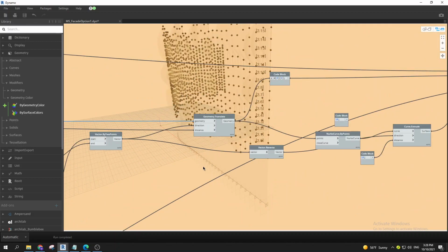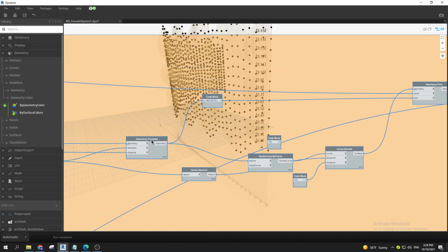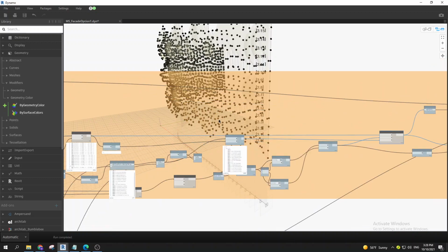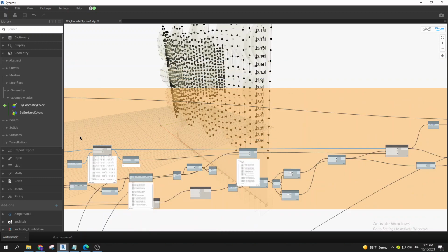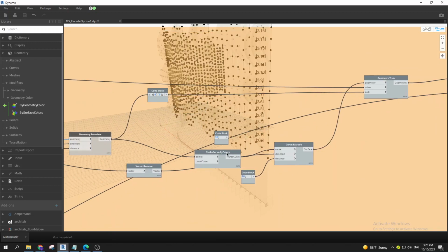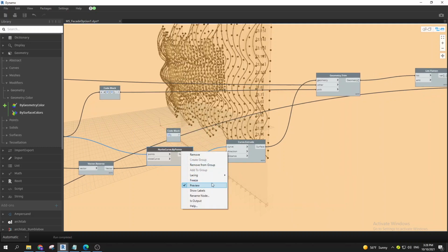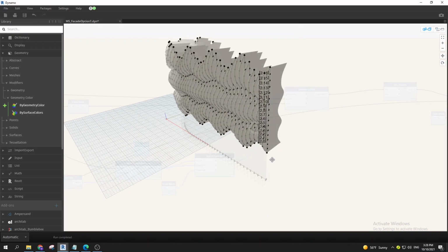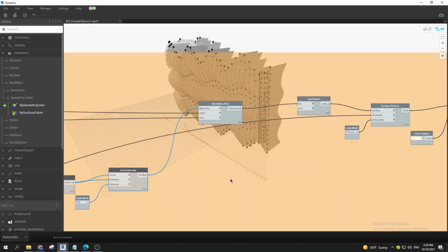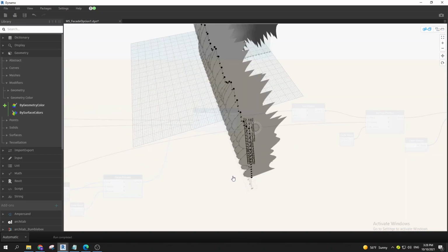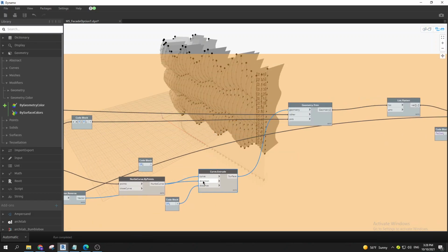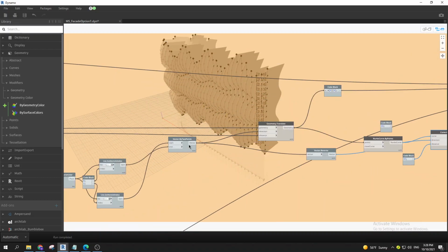And actually from this one it's pretty easy, right? We create Nurbs. So we have these points, we generate a Nurbs, then we extrude this. Let me show you what I do. Then we extrude this on some arbitrary distance, like I've picked the value of 10, it doesn't really matter. So as you can see, I've extruded them. Again, the direction is also by this vector, right?